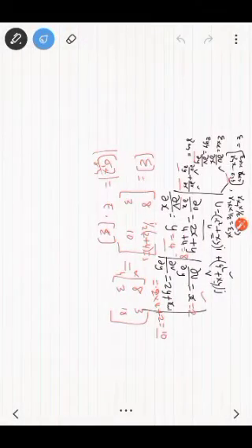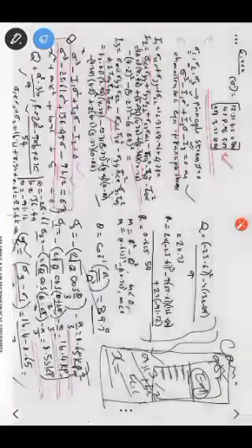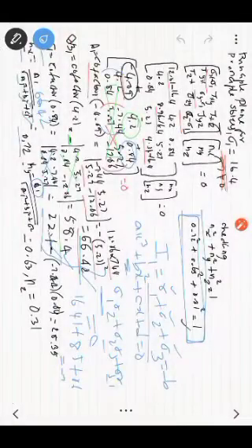So this is the strain along different directions, which can be converted to stress, and from that stress you can determine all the stresses along the x direction, y direction, or any angle, the normal stress, and the maximum stress. By finding the maximum stress, you can check it with the theory of elastic failure and design your material pressure, material diameter. So this is the way, and choose your material, what material you have to choose, that we have discussed in module 5.